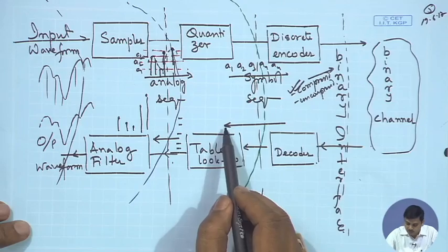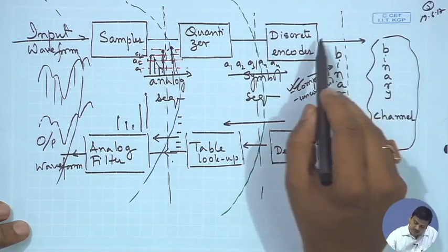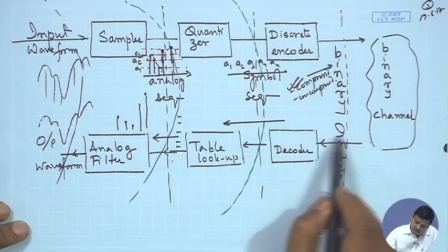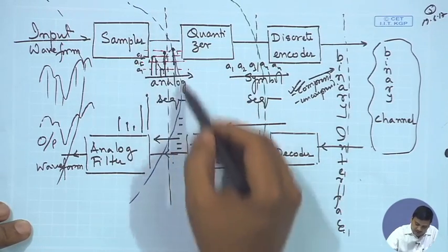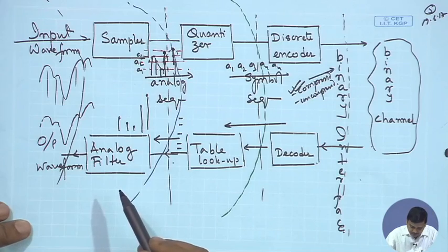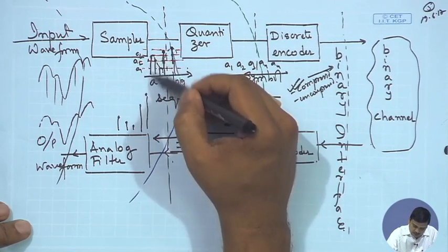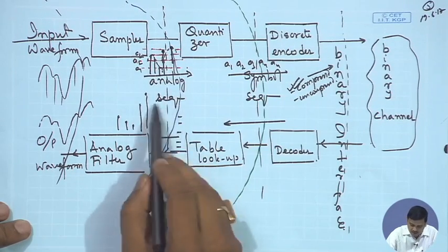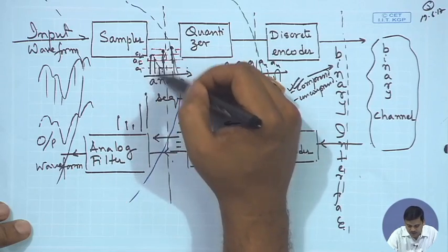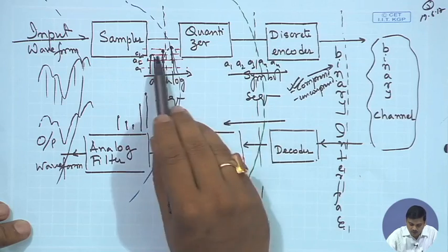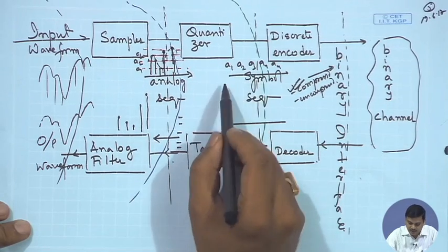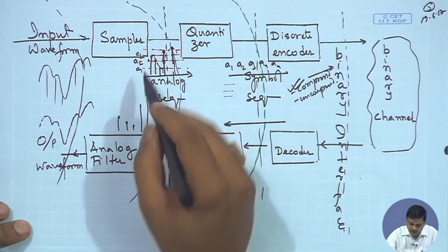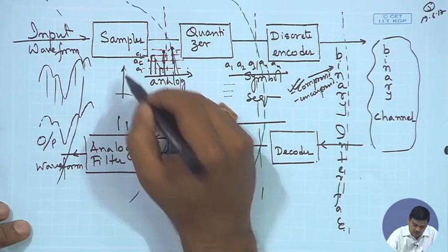What we discussed before is I can think the whole thing is a channel, binary symbols are going in, binary symbols are coming out. These are multi-amplitude symbols. And if we are here, because there is a sampler, these are discrete samples, so analog sequences. Why analog? Because it is just a sampler, so it can take a continuum of values, and this one quantizes these values. So that's the difference between this interface and this interface.